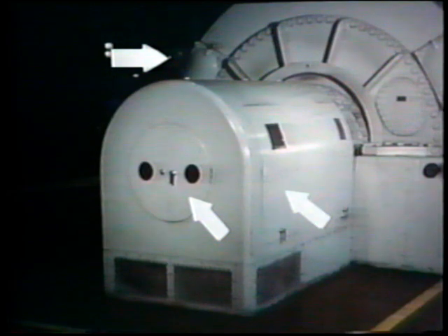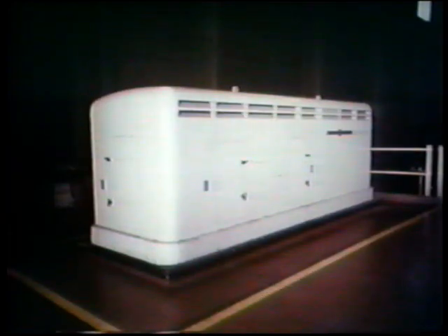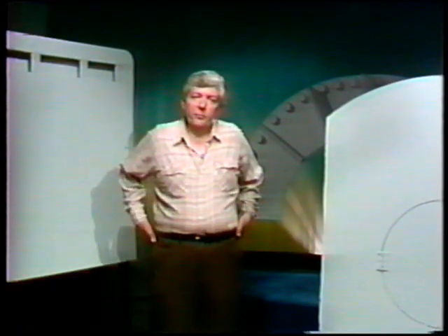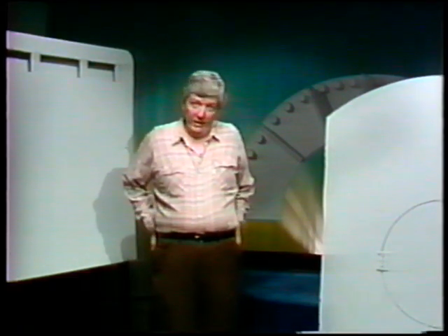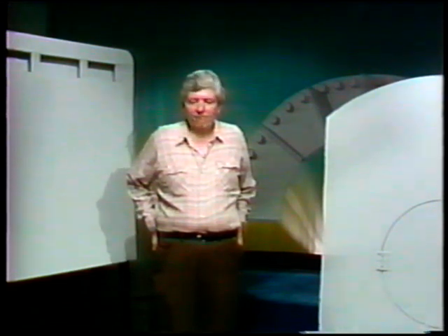Now, this is a fairly common type of setup for an AC generator's excitation system. Another arrangement that's commonly used is a main exciter and pilot exciter driven by a separate electric motor. Here's what that arrangement looks like. With either of these exciter arrangements, the brushes must be checked regularly. This can be done with the system in operation or with it shut down.